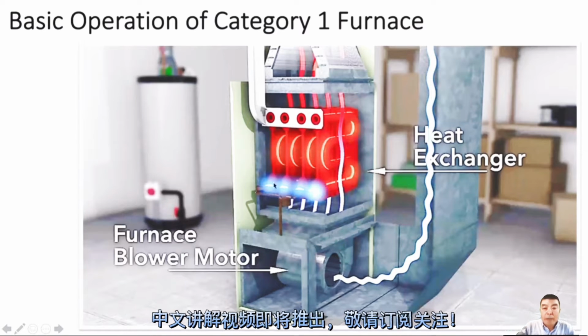At that time we can see the flame just rolls out or is unsteady. If it's like that, we should know we need to check the heat exchanger, be careful. Sometimes we cannot see the crack from the top, but we can use a carbon monoxide detector. When carbon monoxide is detected, normally this means a heat exchanger problem.